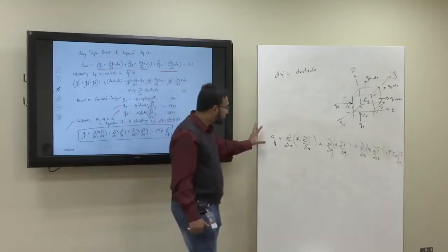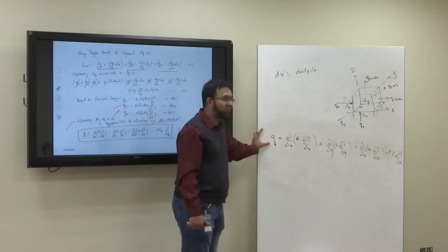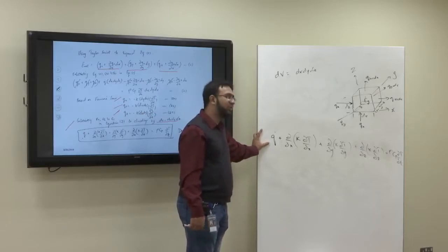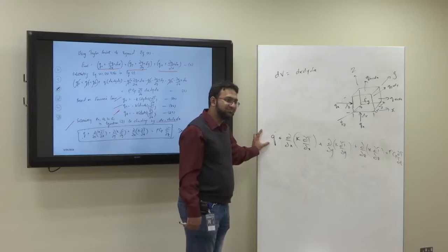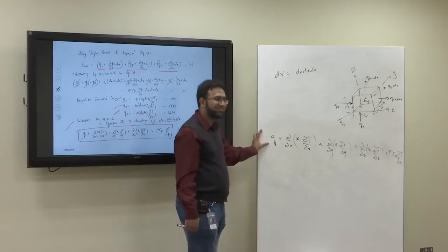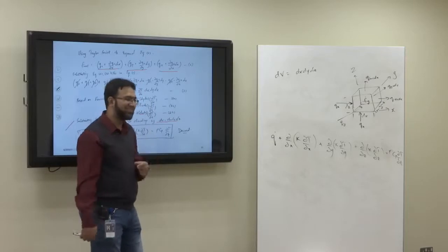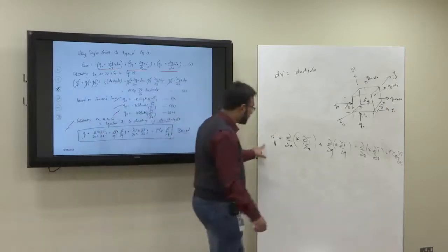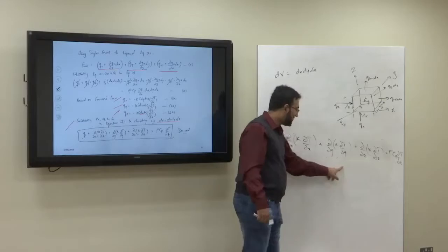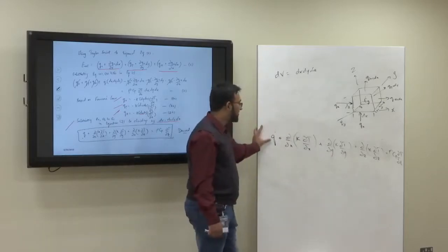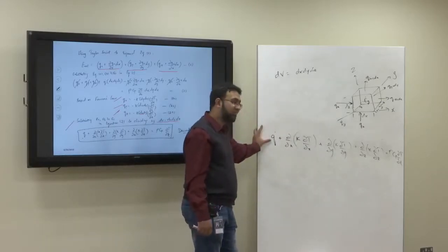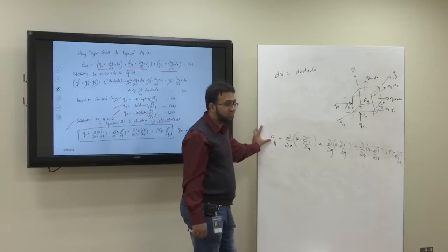So I can bring this equation and ask you to simplify it for an isotropic problem with no heat generation, for 2-dimensional flow and unsteady state. We had a similar question in thermo, I remember. You should understand all these terms here, what they mean, and what will happen if I say it is isotropic material, and what will happen if it is non-isotropic.